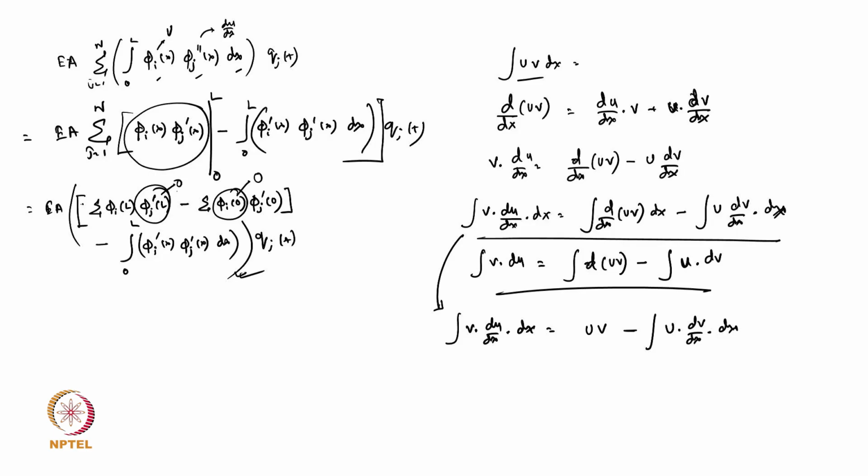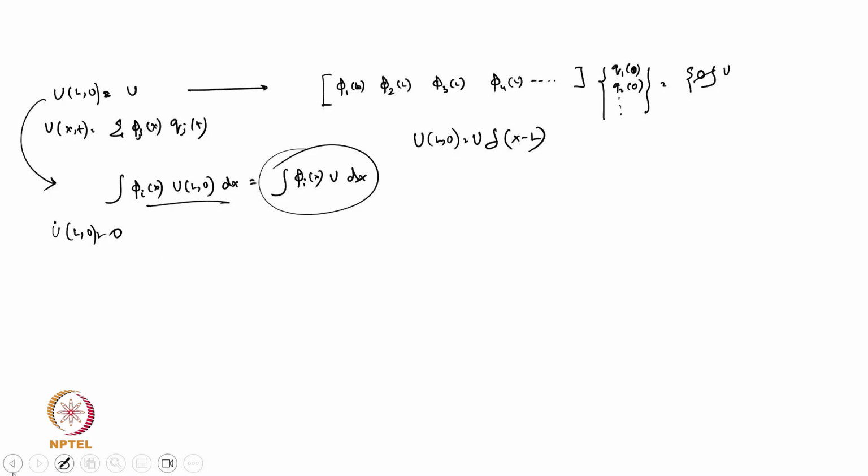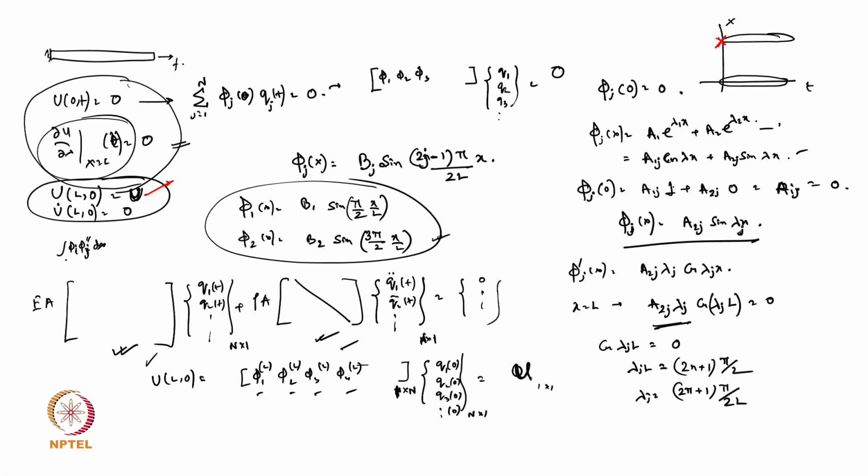So there the effect of the boundary condition went inside the weak form solution. I hope you get the idea of the three methods very clearly, how they are different and how they are coming. Also, here the matrix will be a little bit different, because in the previous case your stiffness matrix was phi i into phi j dash, j double dash.